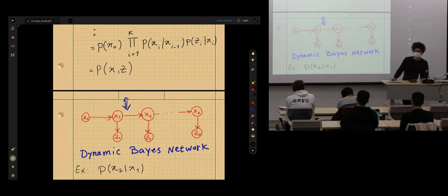This breaks down the joint probability very easily into the product of terms that we wrote down. Without this structure, it's impossible. A more traditional way is to do what we did for robot motion model when we factorized manually by making assumptions and dropping terms, right? Arguably, that's more involved than just visualizing the relationship between variables. So ultimately, when you see this graph, you know how to factorize the joint distribution. For this particular factorization, this is the graph structure. Okay? This makes it very modular and scalable for modeling.